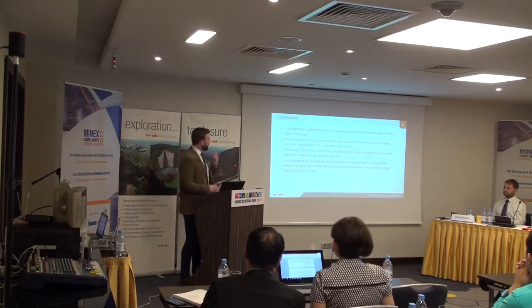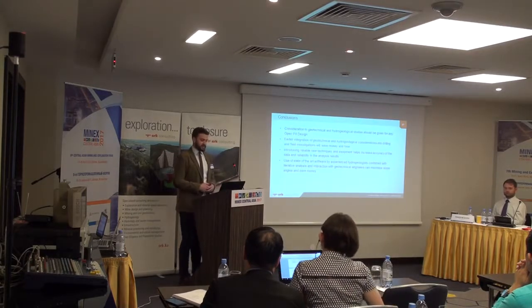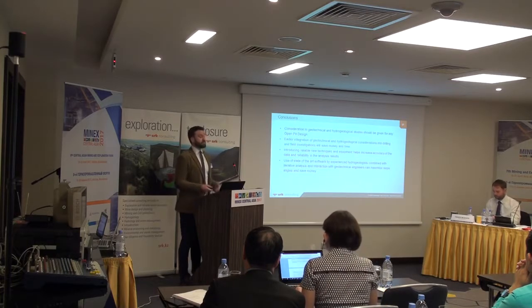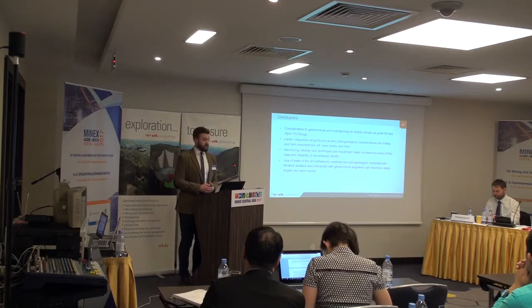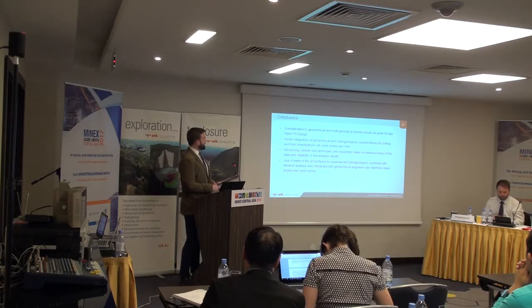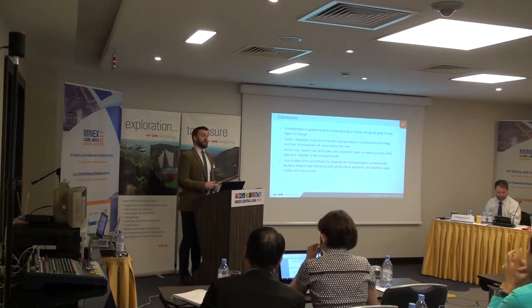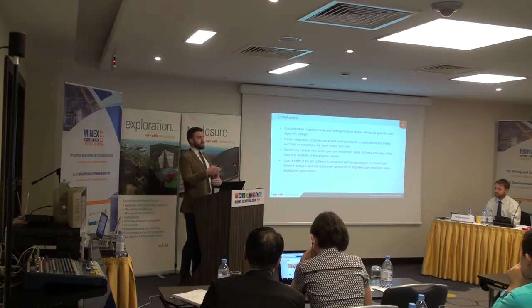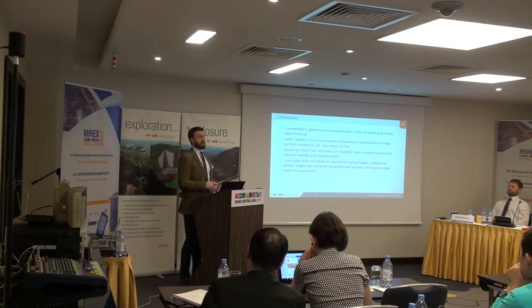So my final slide: consideration to geotechnical and hydrogeological studies should be given for any open pit design and certainly for any underground mine design. And the early integration of the geotechnical and hydrogeological considerations into drilling and field investigations will save money and time. If you have a resource drilling program, I don't see why we're not collecting basic geotechnical and hydrogeological parameters from your resource drilling.